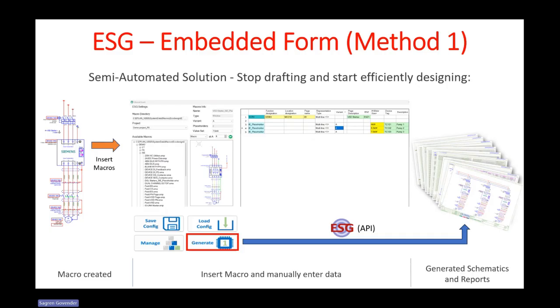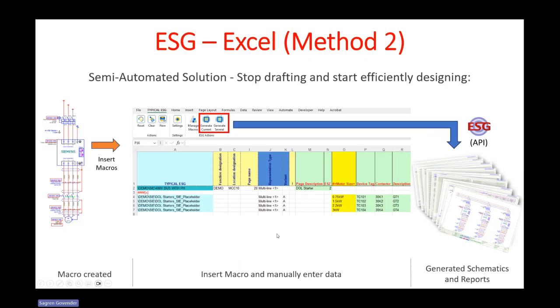But I'll cover 3 scenarios with you. So the first method will be using our ESG, the embedded form method. So there's an embedded form in the ESG. You can insert your macros, you manually type in that information like your tags and so forth, and you then generate the schematic drawings. The second method that I want to discuss is the Excel method, where you